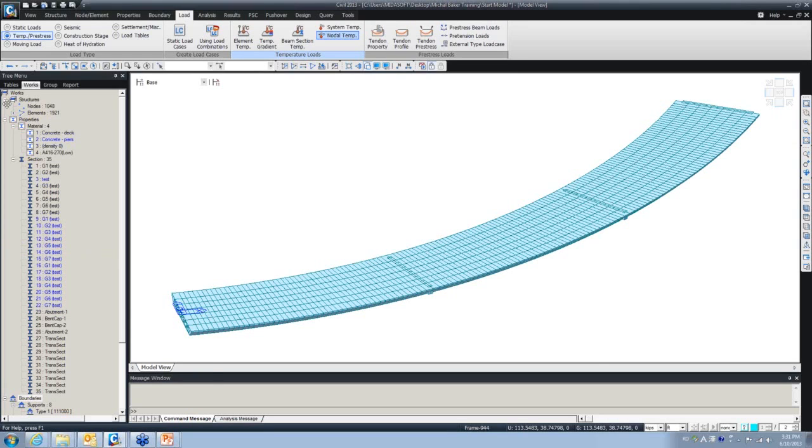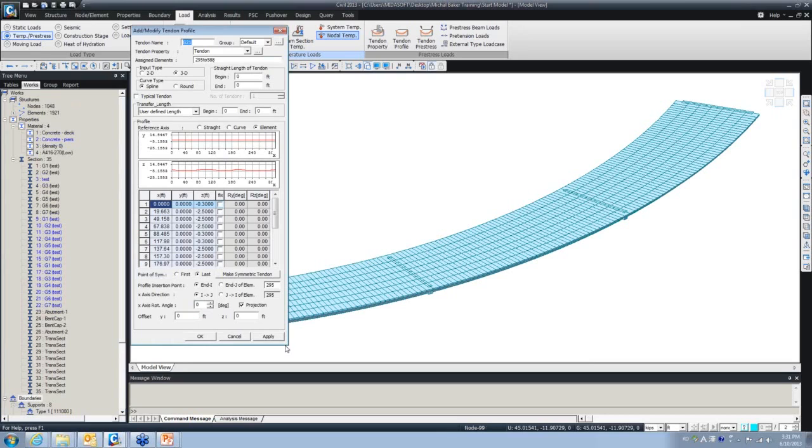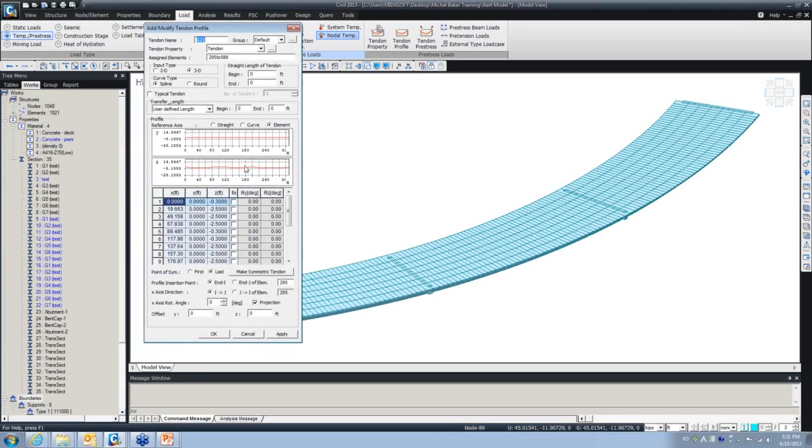All right. So this will be the tendon profile that I want to define. You can see the tendon profile is very small because we have a 300 feet long bridge, so you can't see these changes that much, but when I create it, you can see them better. But you can get some idea about how it's going to look. At the first abutment it is going to be somewhat above the neutral axis, then it goes down, and again on the first support goes up, then down. So you can see that it's following the bending moment diagrams, and we're going to define it that way.